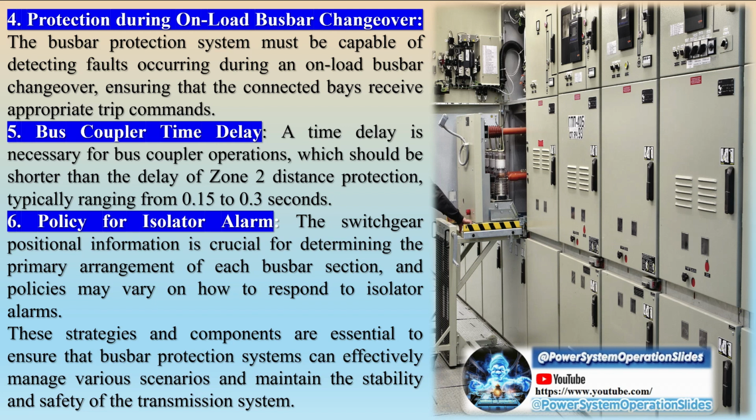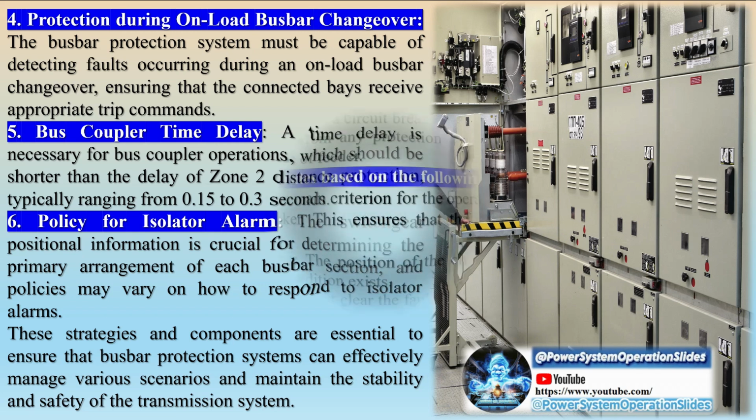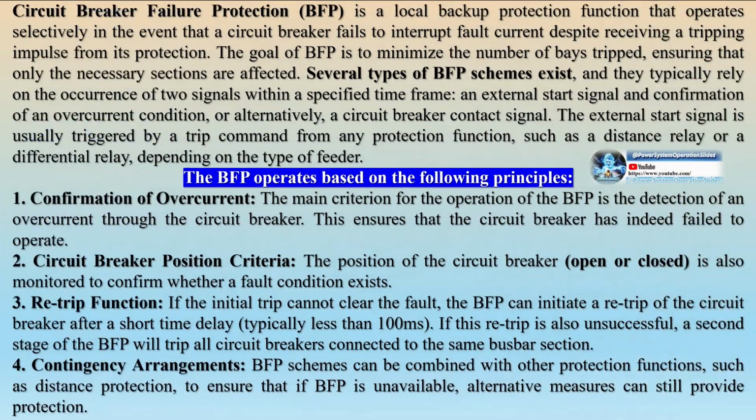There are two other methods to protect these bays: selective protection with delay. This method prioritizes selectivity over speed. If a fault occurs between CTs, only the CB in the bus coupler or bus section trips. Subsequently, these two CTs belong to different zones of the BBP, allowing only the faulted bus to be switched off. A small delay of about 100 milliseconds is necessary to let the CB in the bus coupler or bus section open and for the BBP to reconfigure the substation. The CB state must be signaled to the BBP.